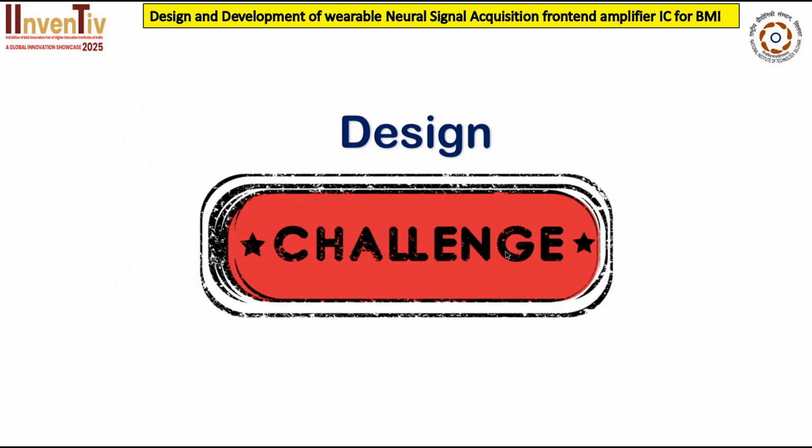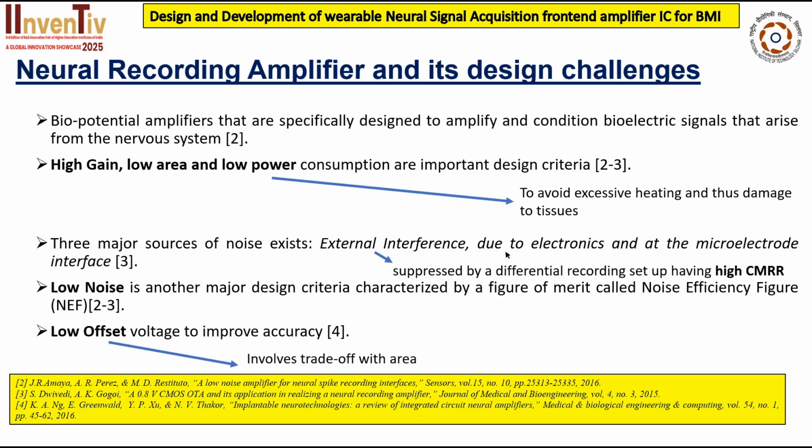Now, design challenges. Every design has some design challenges, so this is also not free from it. There are certain design challenges we will encounter during our designing of circuits and other systems. So these are the neural recording amplifier and its design challenges. You can see here, it requires high gain, low power, and low area to avoid excessive heat and thus damage to tissues, for avoiding the damage caused by the heat.